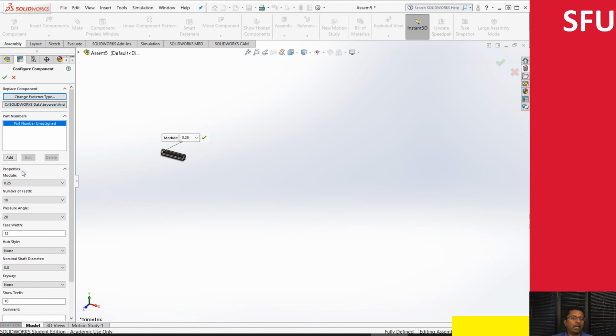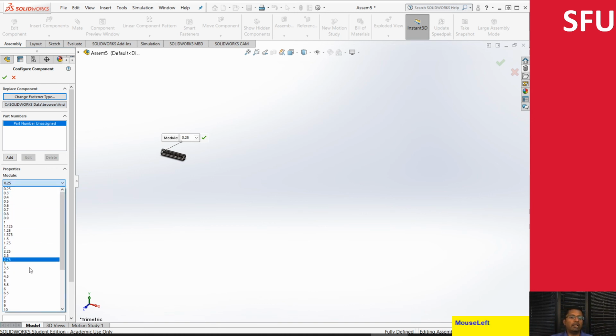Here I have different properties: a module, the number of teeth, pressure angle, and face width. Let's quickly go over one at a time. The module refers to the, quote unquote, size of the gear. These are standard numbers. The module is basically the metric module of the gear, and it determines the size of the teeth.